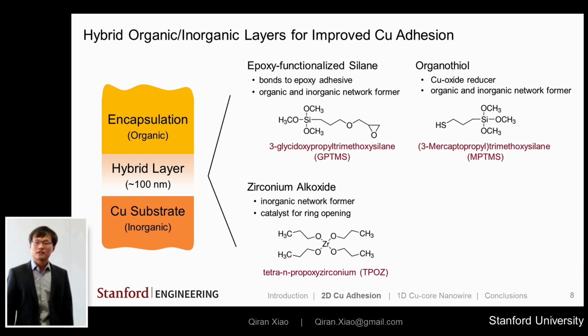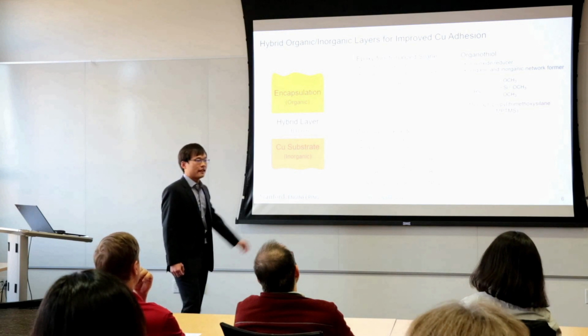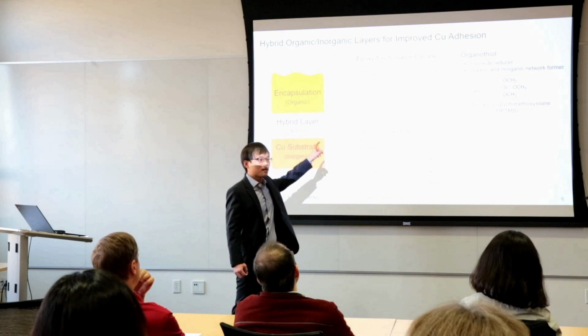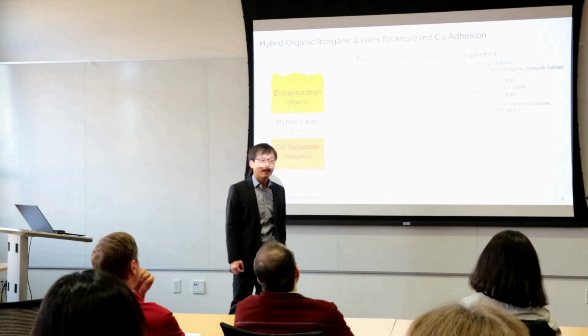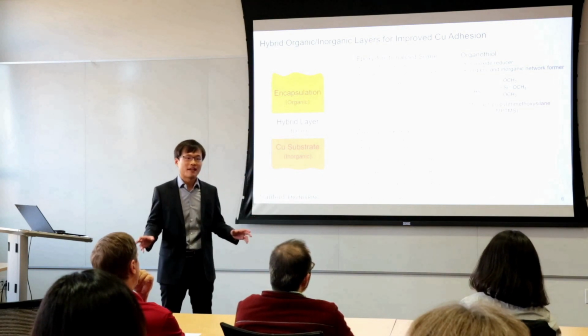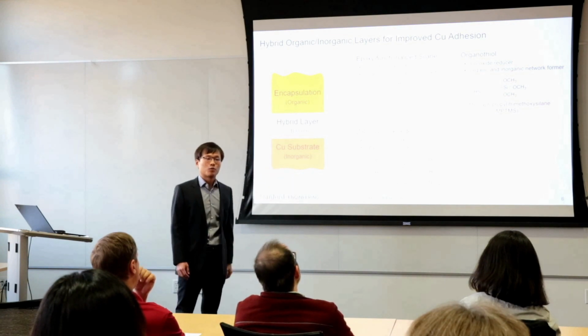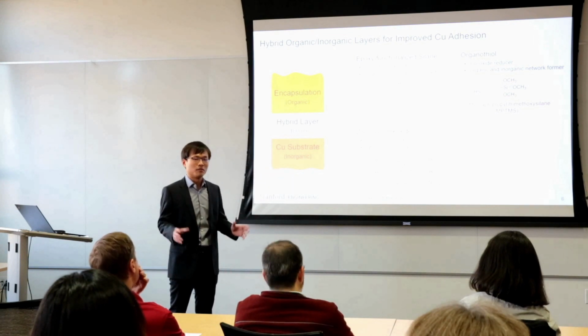In terms of the composition of our hybrid film, it contains an epoxy functionalized silane molecule, GPTMS, which will form the organic part of the hybrid molecular network, and then zirconium alkoxide, which will form the inorganic part of the molecular network.